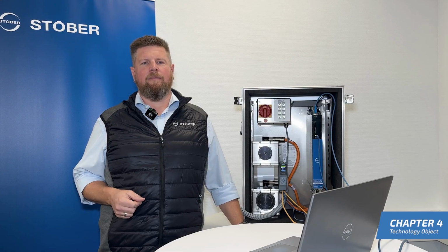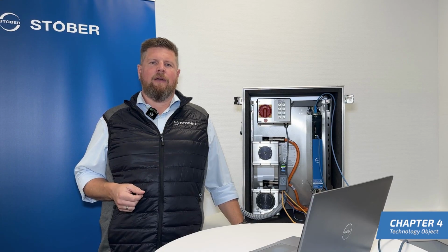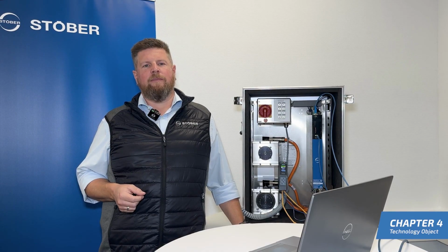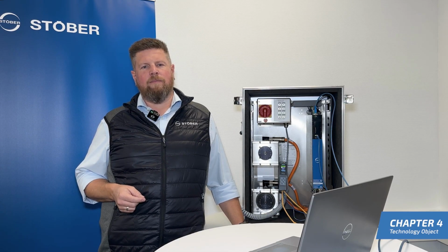What did I just show you? I created a new project in the TIA portal. After that, I installed the GSD file from STOBER and added the S7-1500 controller and the SC6 drive controller to the network view. I interconnected the ports, configured the Telegram with ProfiDrive modules, and activated isochronous mode.